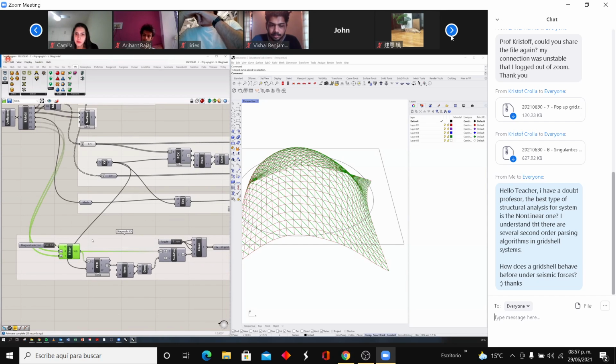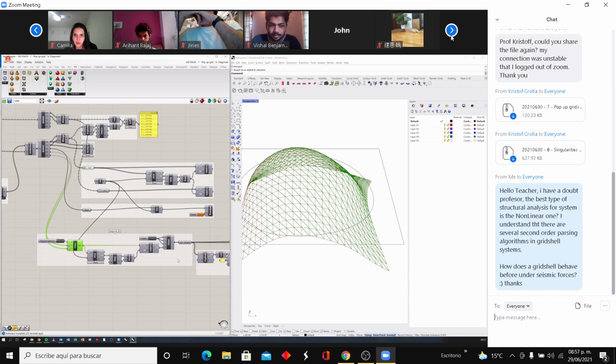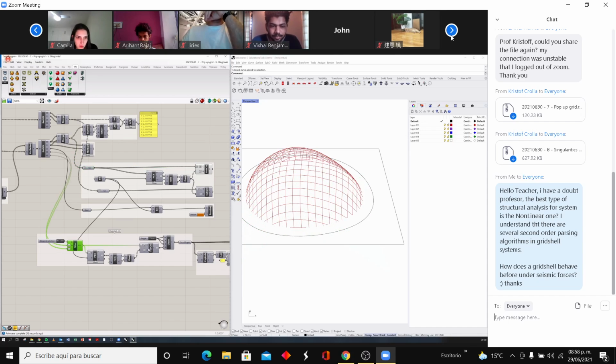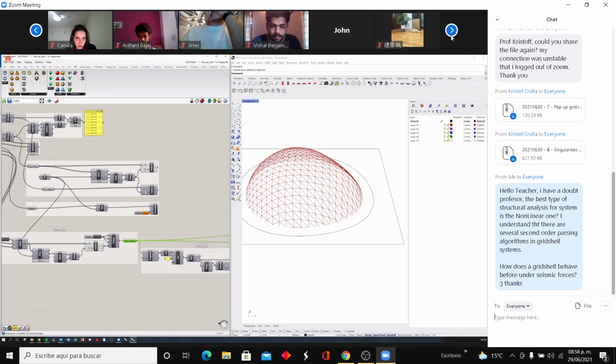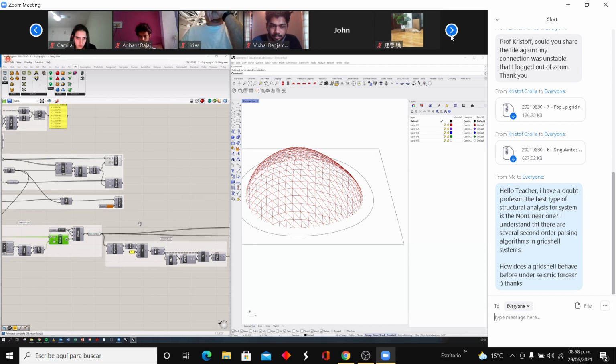And then similar to how I was cutting my base curve grid, I'm using the same plane, same XY plane that I have here, to cut my subcurves here. I'm using the very same plane to cut my diagonals here. And then, yeah, here after cleaning it up, I have my curved three-dimensional grid.